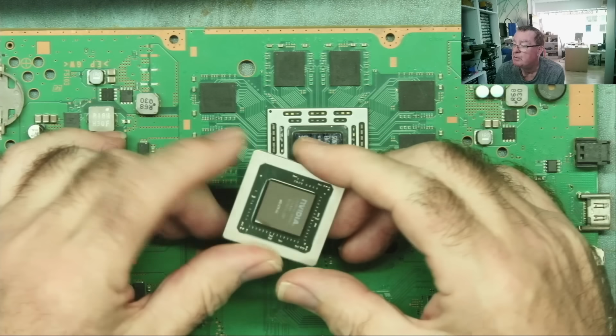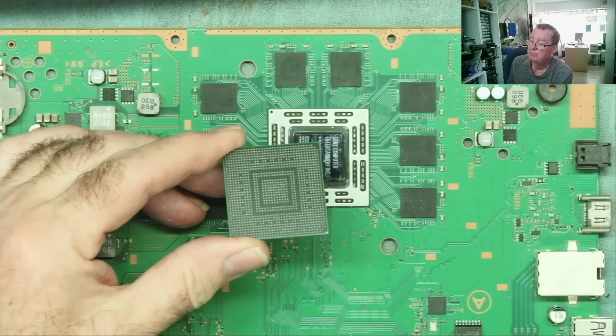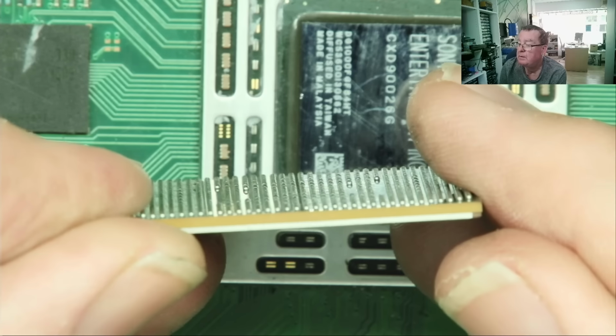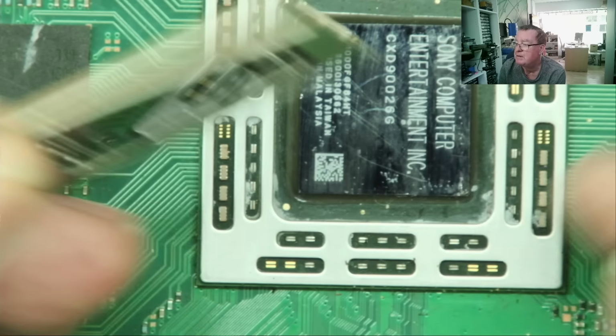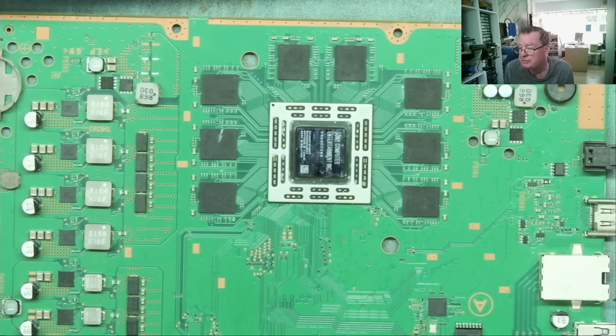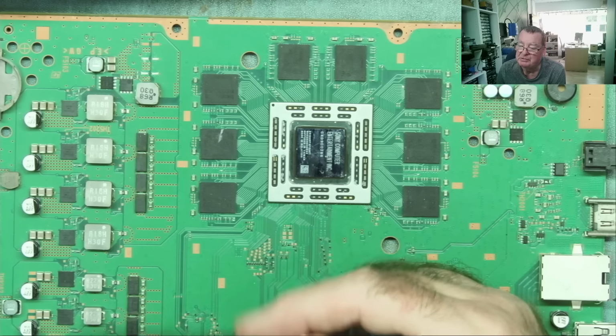So here's a typical BGA chip, okay, and you can see the ball grid array, BGA. As I mentioned, rows and different patterns of solder balls. Can you see them edge on there? So those solder balls are making contact with the PCB. And what can happen, either due to badly designed PCBs or incorrect operating conditions, blocked ventilation vents and such like, we have the same problem we have with the MLCC capacitors.